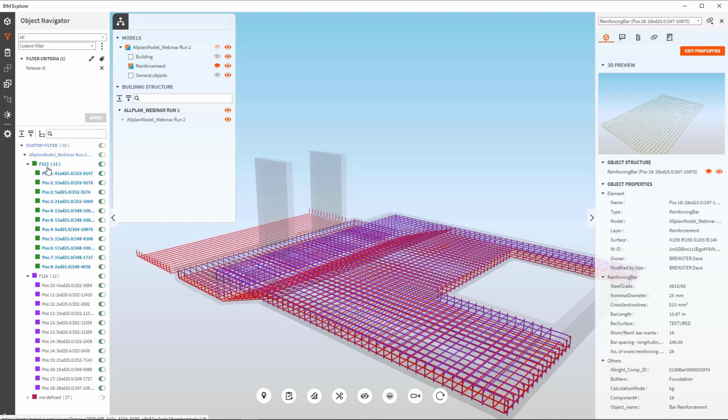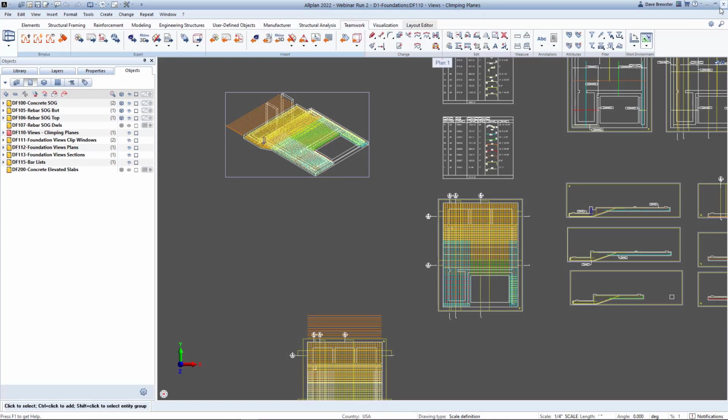So again, this is free. The free version is available for you guys in the field to very quickly go through and look through that for that information. So anytime you're done or you've updated your model, we would simply go back in here, update to BIM Plus. We have options. As you update, you can do an update and track changes where you have different versions. You can update the existing model where you're not tracking changes. Many different things you can do when you upload this to BIM Plus.